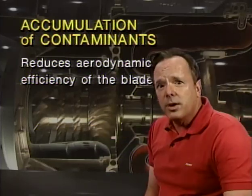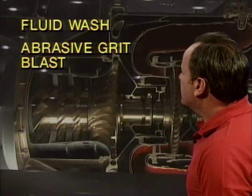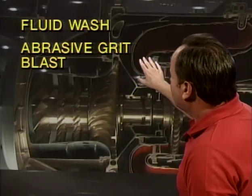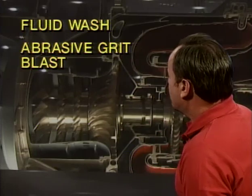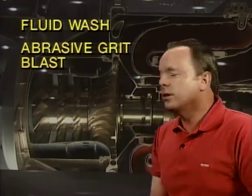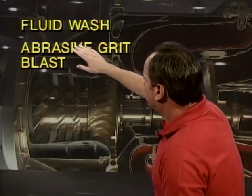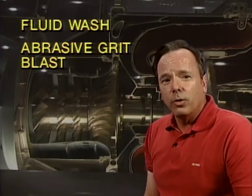So there are two common methods for removing dirt deposits from turbojet compressor blades. One of these is a fluid wash, and the other is an abrasive grit blast. I've heard of people talking about walnut shells. I think you would only have to use FAA-approved walnut shells. But those are the two ways to clean compressor blades: a fluid wash and an abrasive grit blast.